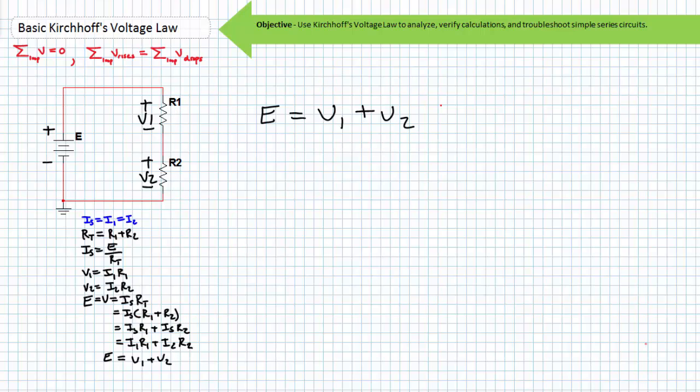This should have been very easy to understand, and we'll return to an extremely powerful application of these results in a second. I've yet to prove to you that you can KVL things the dumb and hard way and still get the same results. Let's start here. This would be dumb. And just to be obstinate, let's go in this direction, counter to the flow of conventional current. This would be hard. And away we go. Leaving our poor choice of starting points, we enter the negative terminal of resistor 1 and come out the positive. This is a rise of the value V1. This goes on one side of the equation.